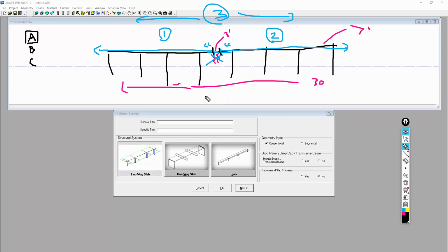So in this program, which is primarily built for post-tension structures, tendon A goes from this end all the way to this end. It could be a dead live, it could be live live, or live dead in terms of the anchorage. And here I'm just drawing these flat. In reality, they're going to have some sort of shape to them. So because tendon A passes through this pour strip, we can't really use it.